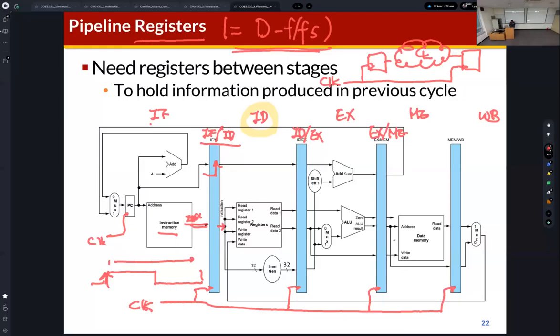So, the rising edge of the clock, right? And so this is the clock signal here. So the sampled data, the sampled instruction in this example, is given to the ID stage. You can find some data path here. So the instruction is here. This sampled instruction data is given at the rising edge of the clock, and then it is given to the data path element.